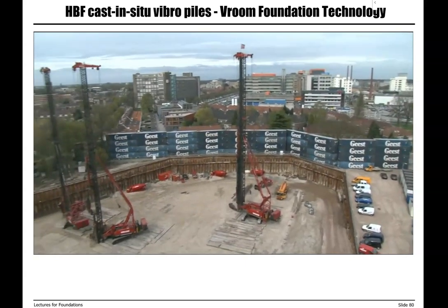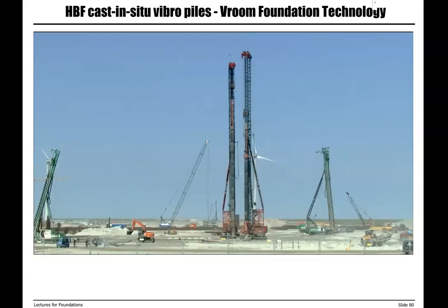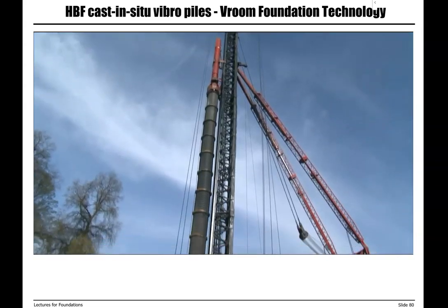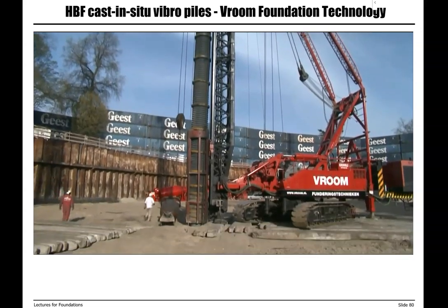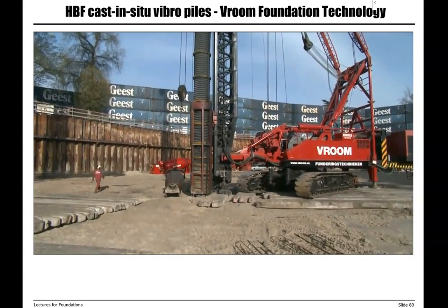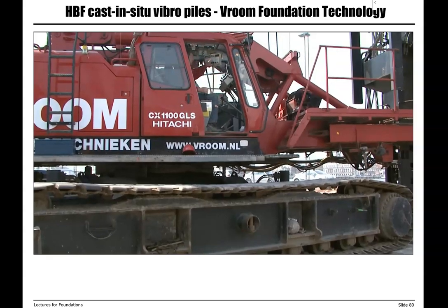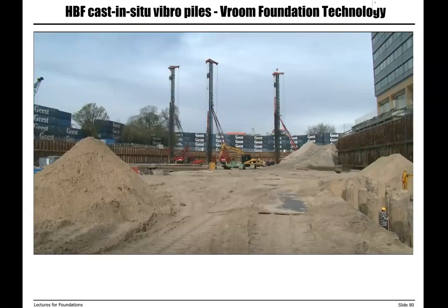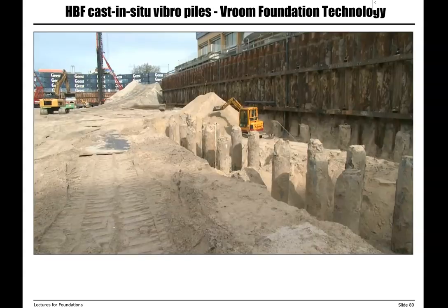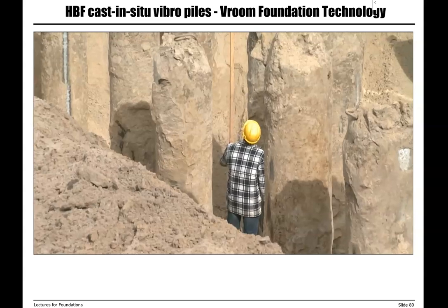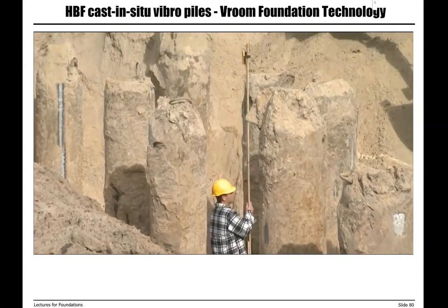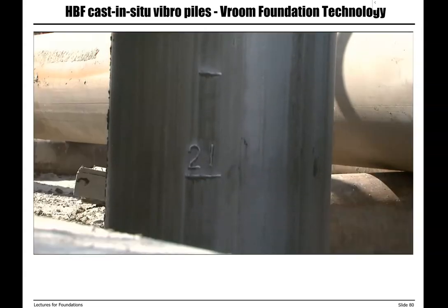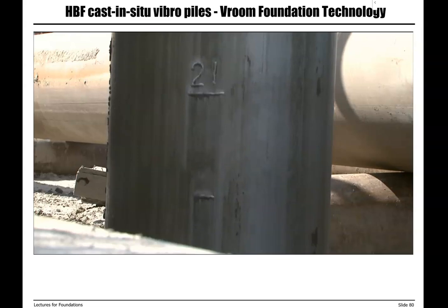Type HBF vibra piles are cast in situ driven displacement piles. Vroom van Dieringstechnieken has various types of hydraulically driven piling rigs for pile driving the casing in which the concrete pile is produced. The advantages of vibra piles come to the fore during changing soil conditions, longer piles, or when using piles which are subjected to greater loads. The shape of the vibra pile is based on the bearing capacity needed and soil condition. The depth of the casing to be pile driven is determined by the soil structure.